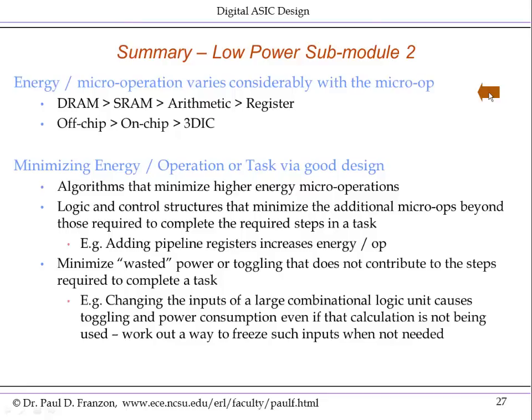The trade-off here is that you might, for example, not pipeline a design in order to reduce its energy per operation, which means, unfortunately, that it will be slower as well. So there is some penalty to doing this. You might be slowing the design down, reducing the amount of microparallelism in order to reduce the energy per operation. Also, I remind you, in terms of data communications, off-chip is worse than on-chip, which is worse than 3D, if that's a technology that's accessible to you.